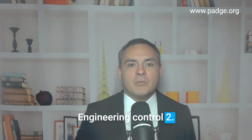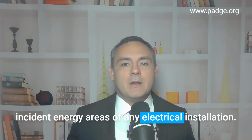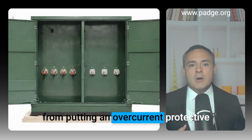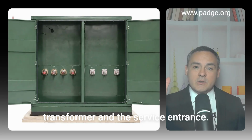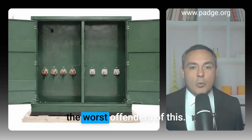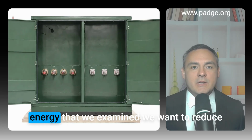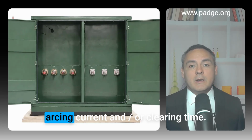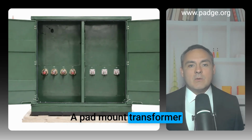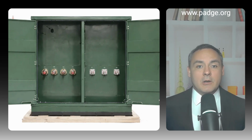Engineering control 2. The service entrance is one of the highest incident energy areas of any electrical installation. This is often because many people defer from putting an overcurrent protective device between the service entrance transformer and the service entrance. Renewable energy is one of the worst offenders of this. Recall, in all the equations for incident energy that we examine, we want to reduce arcing current and/or clearing time. A pad mount transformer will allow massive amounts of fault current on the secondary before the primary devices clear it.